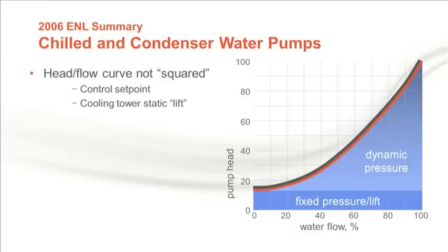This chart shown here provides an indication of how these fixed pressures keep the pressure drop from changing with the square of the flow rate. In addition to this pressure not following the square relationship, there are minimum flow requirements. During normal operation, the condenser water side flow rate must be maintained above the higher of the chiller condenser minimum and the cooling tower minimum.